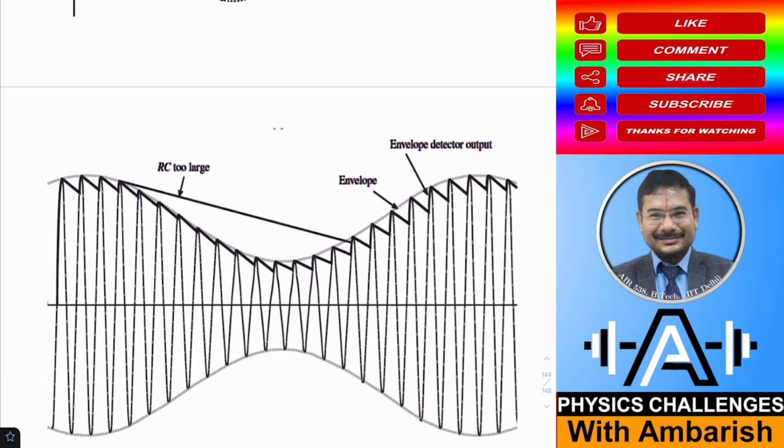Capacitor was discharging, but even after discharging, the voltage of capacitor was always more than the peak voltage of the AM signal. So that means what? The diode never got forward biased all the while. So you missed out all these peaks. Why? Because capacitor was already having more voltage than the AM signal, and diode was always reverse biased. All these peaks got lost.